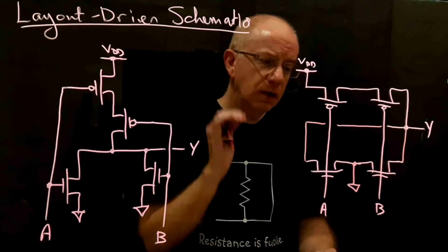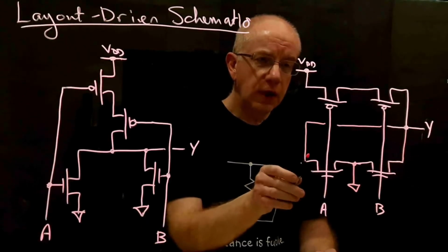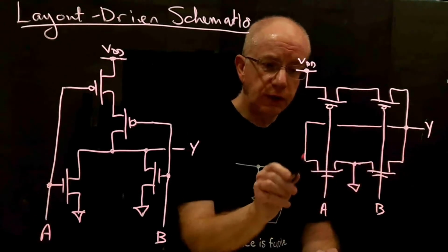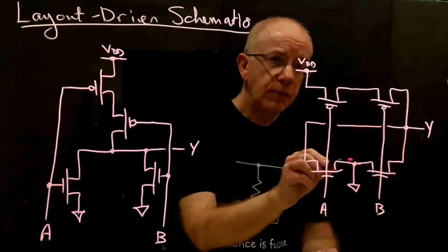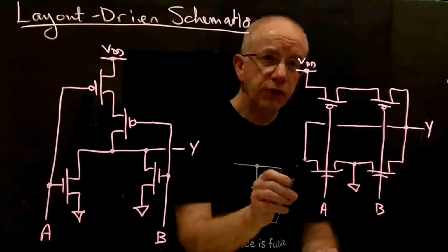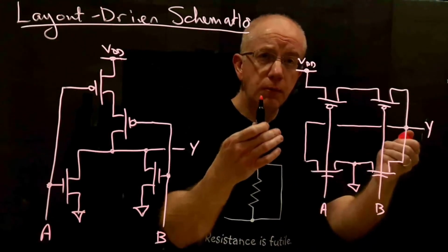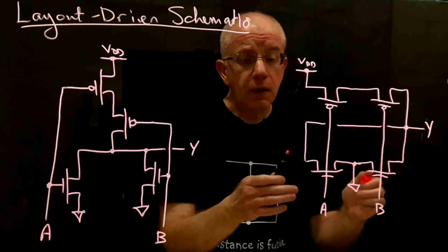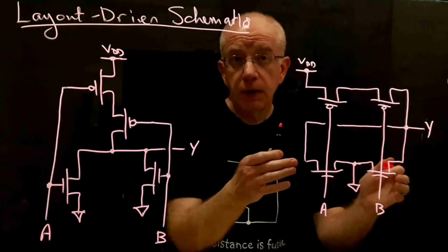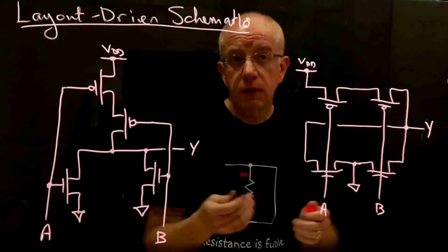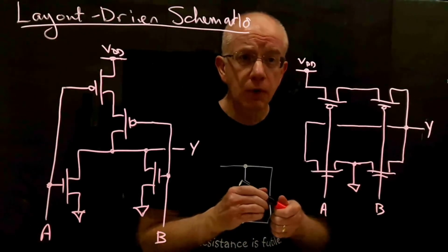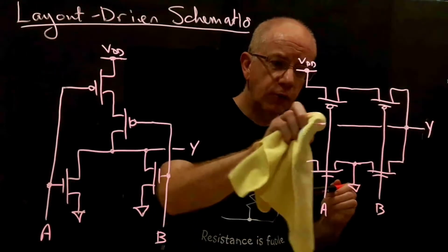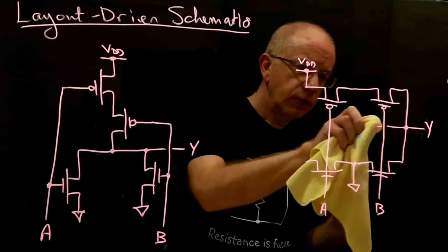But of course that doesn't seem like that's going to be a great idea, because we're putting more capacitance on the output node from this drain and this drain than if we tap it off in the middle, and we don't have ground on the outside of the cell, so that it might be able to be shared with or merged with, let's say, a ground substrate contact on either end, or maybe share a ground tie with an adjacent logic gate or something like that. Okay, so this one I wouldn't think is as good as, or preferable to, the one I started with here,